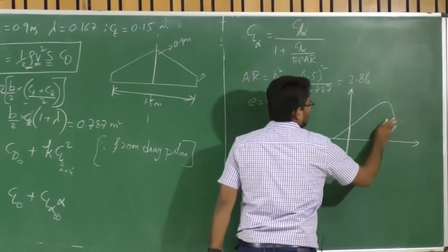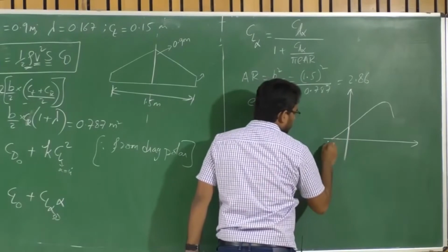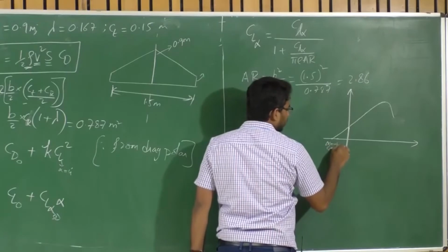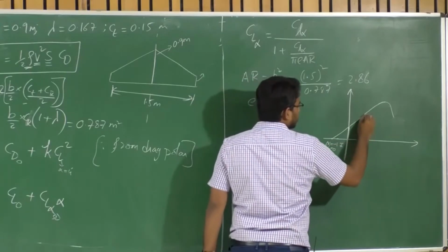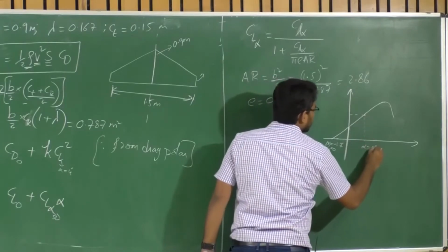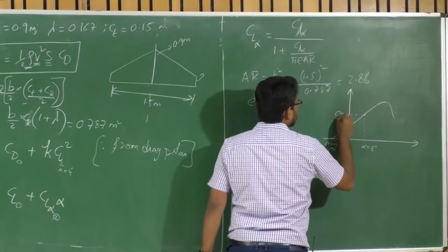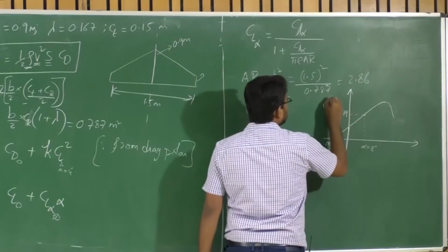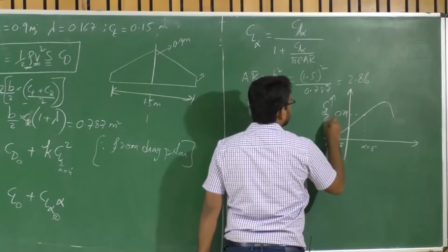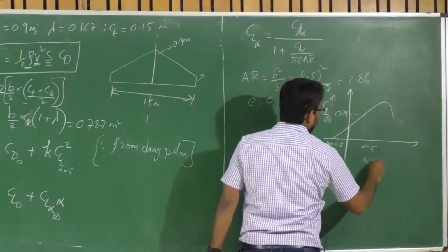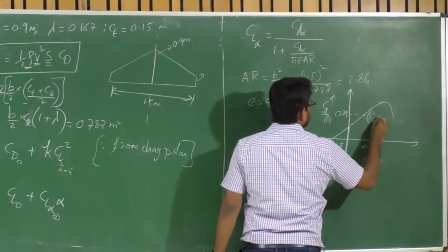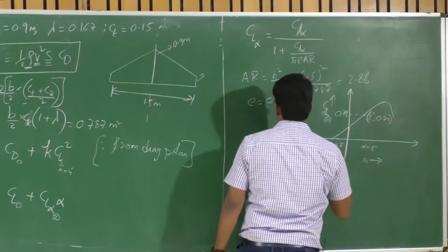Okay, so alpha at which CL is equals to 0. So this is minus 1.7 degrees, right? And then CL at 8 degrees. Alpha is equals to 8 degrees. So the corresponding CL value is 0.79, right? This is CL 2D case, right? CL 2D and alpha. So the coordinates here are 8 degrees and 0.79.